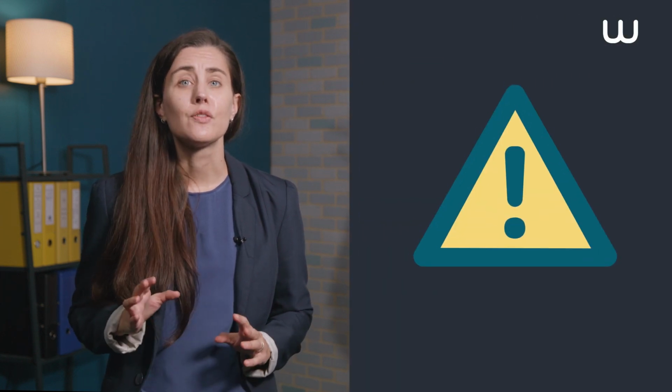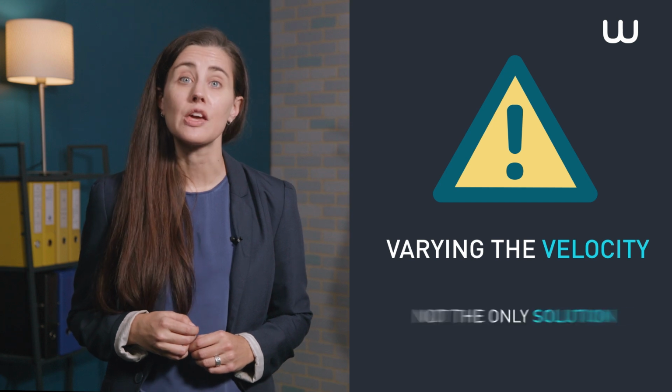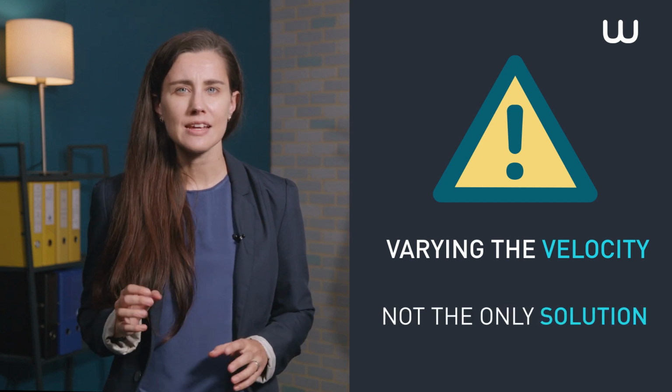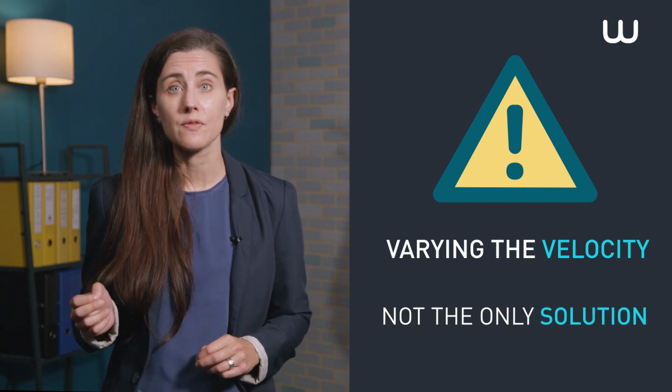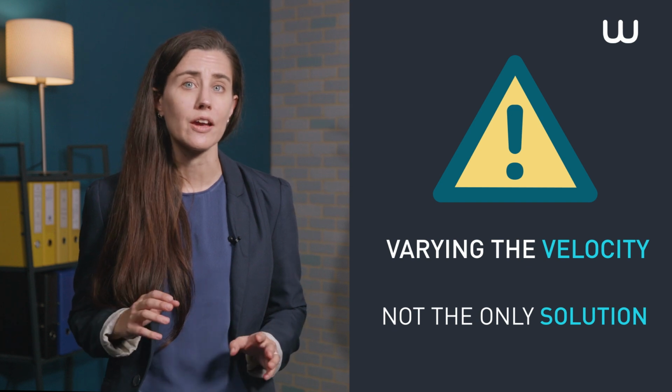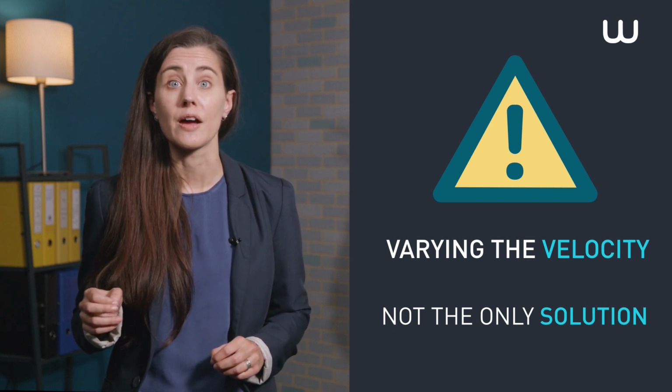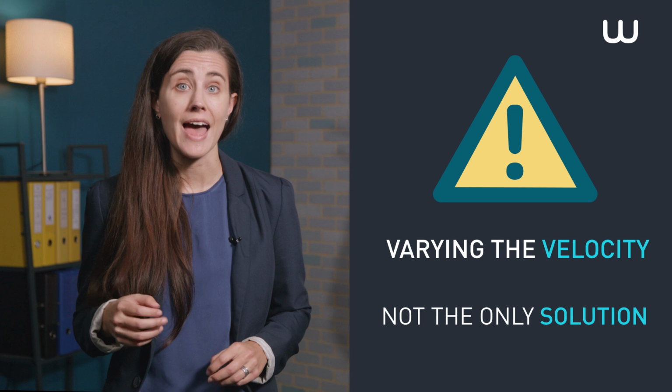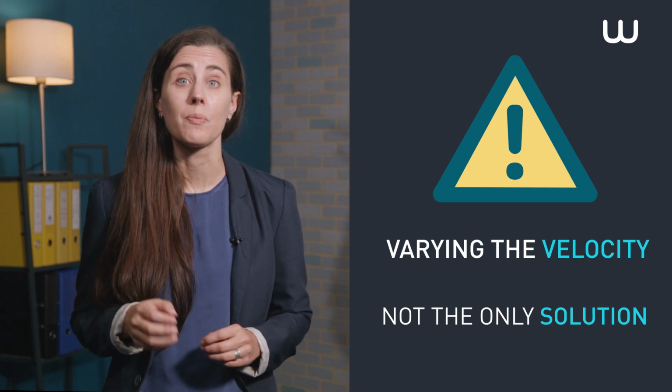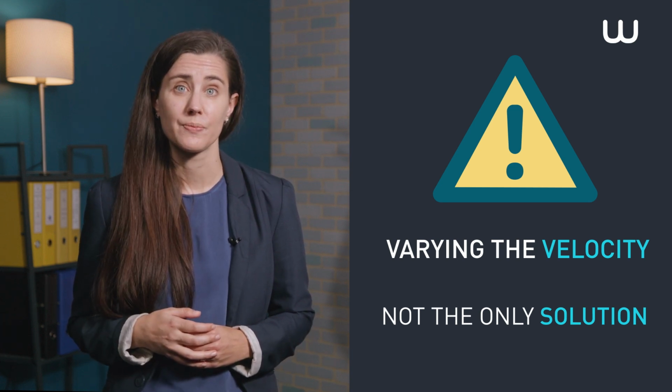Therefore, a detailed technico-economic study must be systematically performed to find out if the variable frequency drive will enable the pumping station to be optimized in hydraulic and energy terms. Varying the velocity is not the only solution. It is necessary to check that the overall savings in electricity is indeed higher than the variable frequency drive's electricity consumption, and the possible decrease in the pumping unit's overall efficiency.